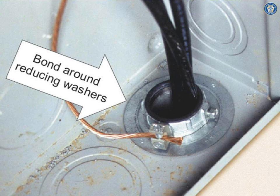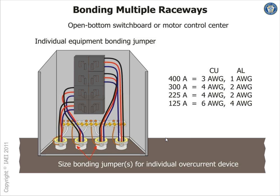Concentric, eccentric. Here's the bonding, because these are concentric and eccentric knockouts are encountered. You have to supplement the bonding with a bonding jumper. You see them all the time here.